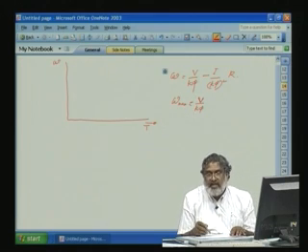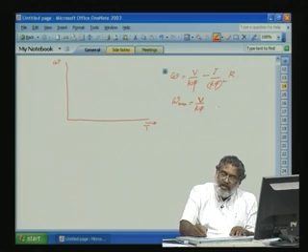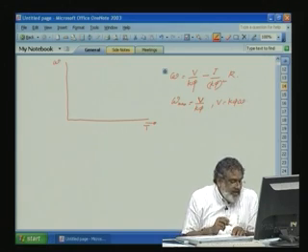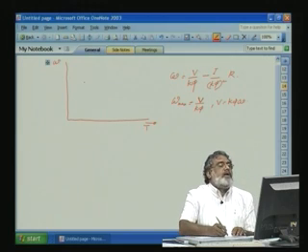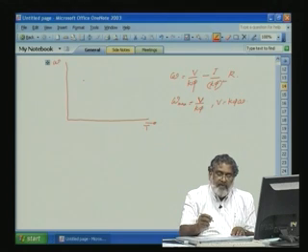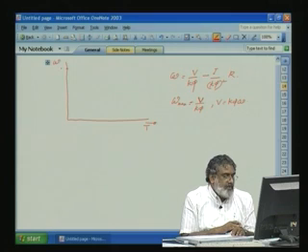So, here also if you see, this is also equal to the maximum back EMF. When I is equal to 0, the IR drop is equal to 0, V is equal to EB. So, that means V is equal to K phi into omega. Okay. This is the back EMF. So, V will be equal to back EMF. Now, let us plot the torque speed characteristic for a particular V. So, we have fixed the V. Once V is fixed, and EB is equal to V, we have the maximum speed here.